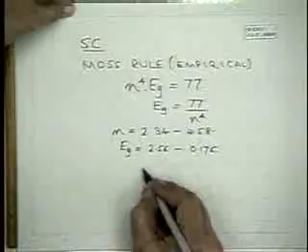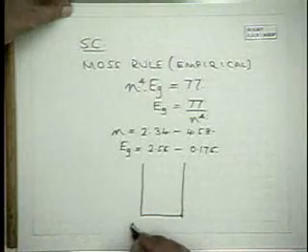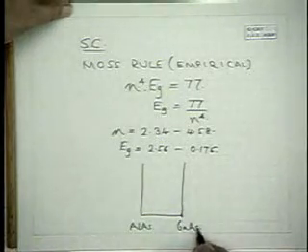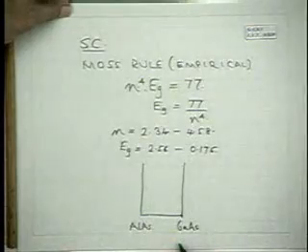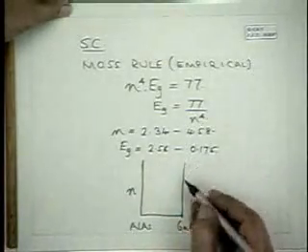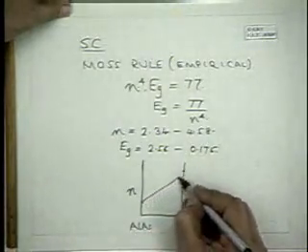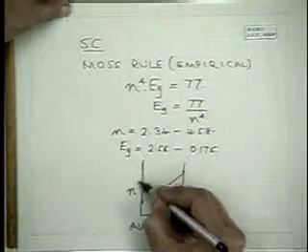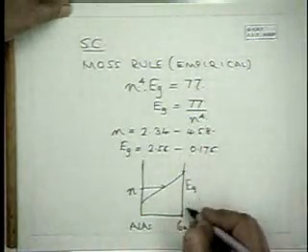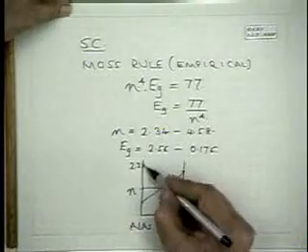We'll go back to this later. The refractive index of aluminum arsenide is lower than that of gallium arsenide, and the band gap is, on the other hand, if you plot the band gap, 1.4, and this is of the order of about 2.2. Okay, so you get some variation like that.